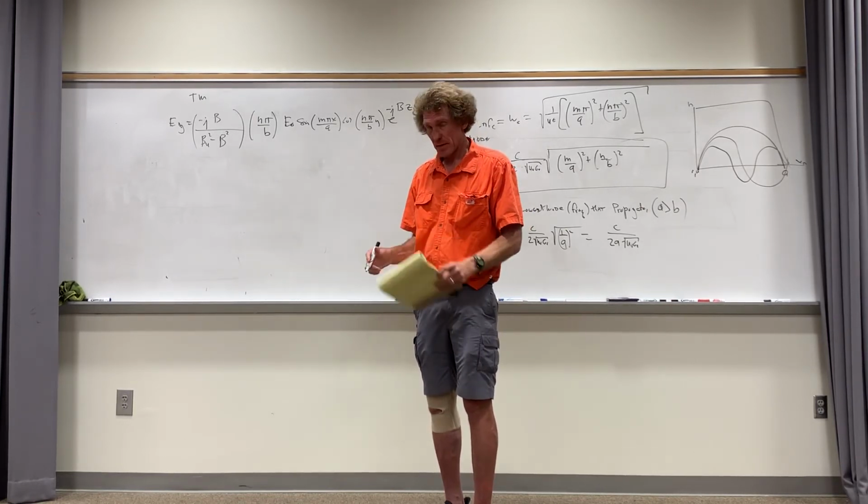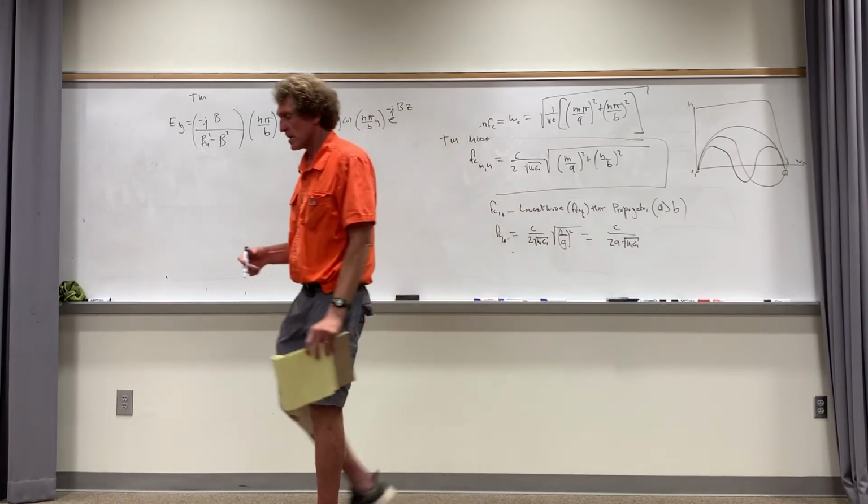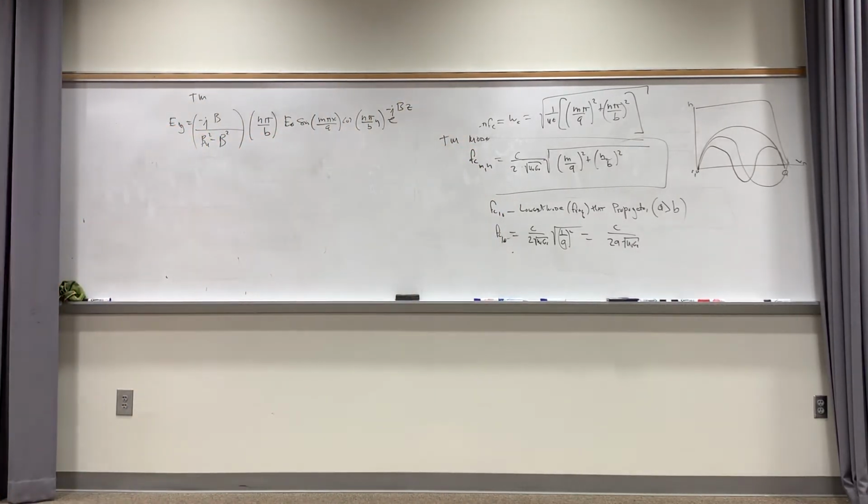Something else I want to say, I want to try to hit all the things. When we talked about transmission lines, which you could say is a waveguide in a sense, but it's not really, because a waveguide means you have wave phenomena that's ricocheting. In a transmission line, you don't have that. You've simply got a plus and minus voltage where the actual wave is propagating that way, but it's not something that's bouncing up and down. It's going only in that direction. Do you follow me?